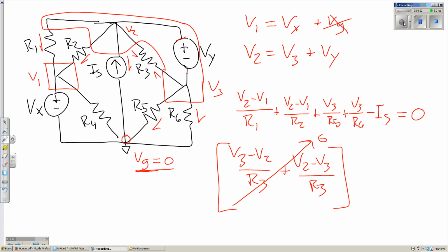So let's recap. We first identify our nodes. The nodes are places where 3 or more currents branch. It's not a point, but it's segments of these wires. And if you look in the old tests, a lot of them ask you to identify where the nodes are, and those are colored in. Check those out. You can see what I mean here, why this whole area is our node. Okay, so step 1, identify nodes.